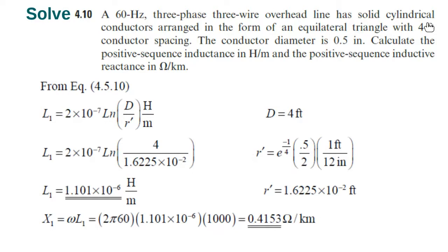We did not discuss the stranded yet. This is solid cylindrical, that's why the inductance is constant there. We write it as R prime, the radius prime, times 0.7788.